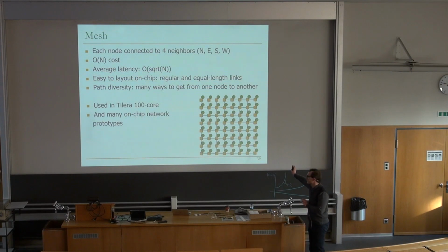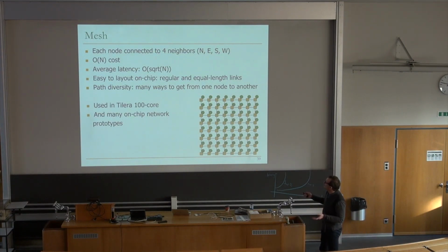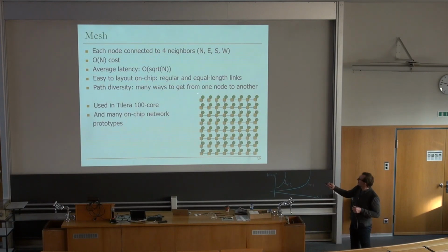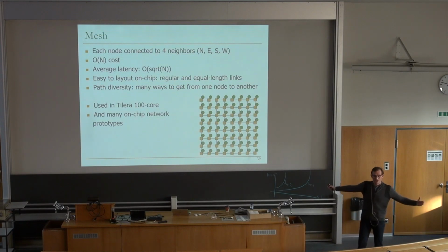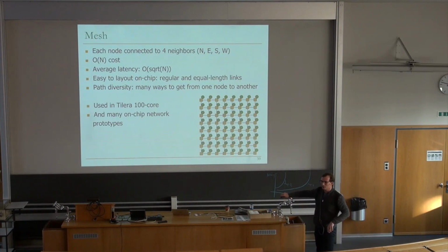Okay, so mesh is very interesting, clearly. And if you have a packet switch network, this is beautiful. But you could also use circuit switching on top of that. I'm not going to go into the detail. But one of the issues with mesh is the drop-off on the corners is pretty bad. So if you're a poor thread that's mapped to the corner, essentially you're crippled. Why are you crippled? Because you have only 2 connections over here, right? Whereas if you're in the middle, you have 4 connections. You can basically communicate on all dimensions. Whereas if you're on the corner, you can communicate only with essentially the south and the east here, right?